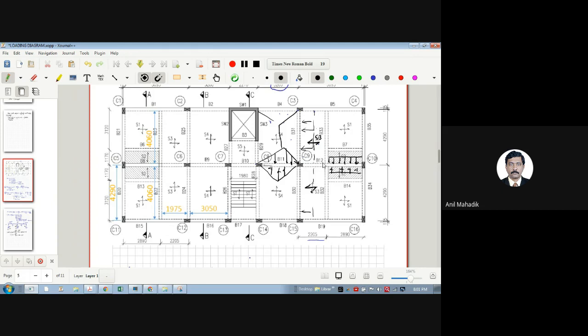So what loads will be there? From S4 a triangular load here, then within this zone there is no load. And please understand there is a secondary beam there, B32 and B33. So there will be point loads from B32 and B33. Correct?